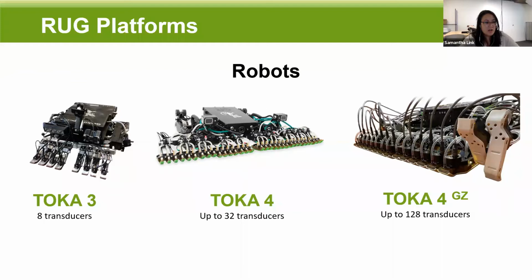And so does RUG adhere to the API 653 inspections? So to that question, that's kind of an involved question. API 653 will allow ultrasonic robots for floor scanning. I think that's what the question was asking or intended to touch on. API 653 says that you can use MFL, you could use ultrasonic testing methods, and then it lists out the defects that you need to test for on a tank floor to have a good integrity program.